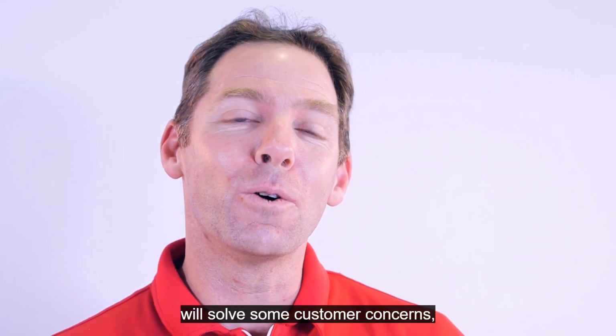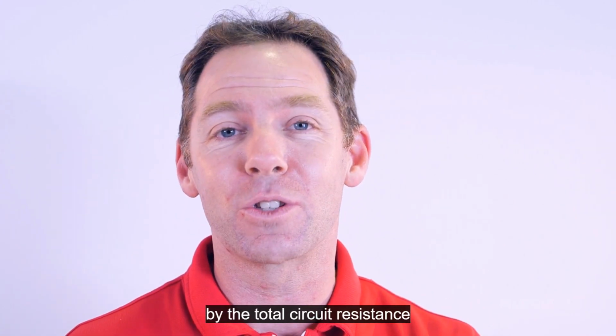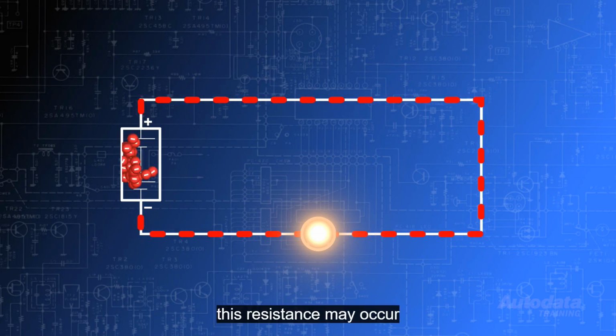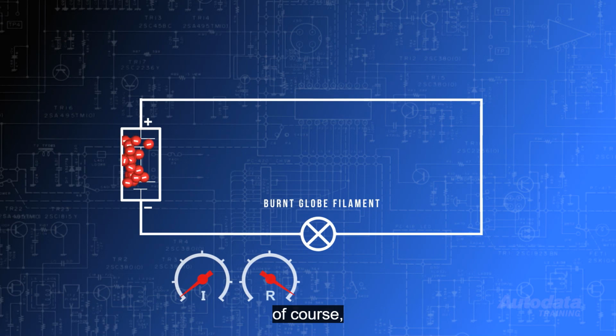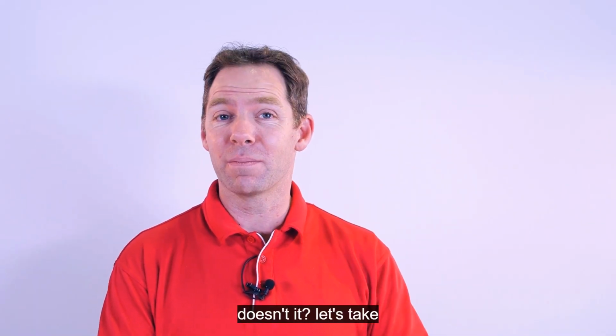And while this will solve some customer concerns, most of the time the problem will be caused by the total circuit resistance. This resistance may occur in the load itself, like a burnt filament in the globe. What would change in the total circuit resistance? Of course, it would be an open circuit, and the resistance would measure as infinite. So, what happens to the current flow? It drops to zero, doesn't it?